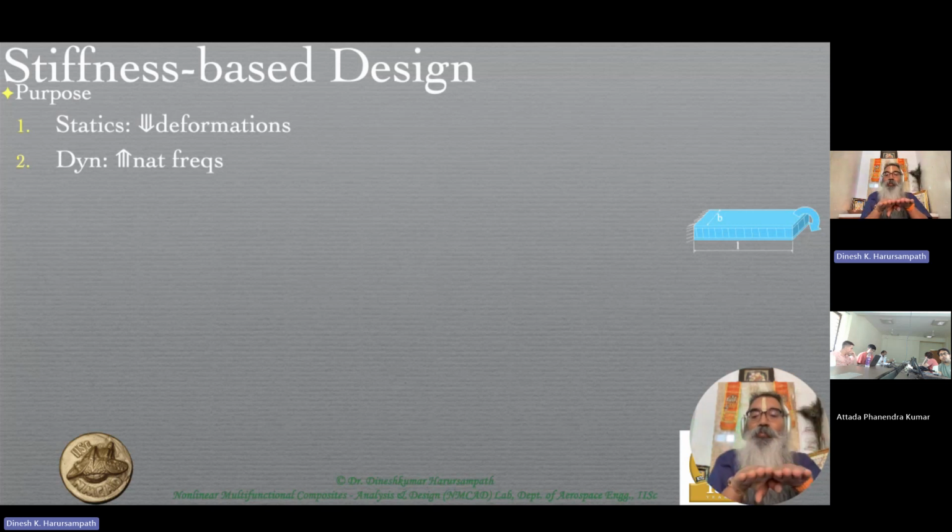So essentially, the tip plane of the rotor blades is tilted towards the back, and therefore the net thrust from the helicopter rotor has not only a vertical component but also a slight horizontal component towards the back, and the helicopter will start moving rearwards. Similarly, you do exactly the opposite to tilt it forward and move it forward.